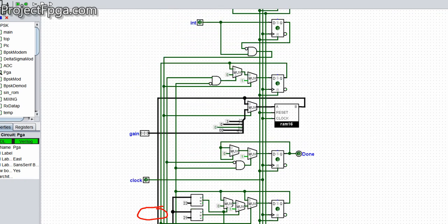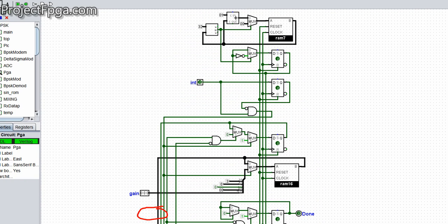The first part of this circuit is the clock frequency divider. Just like I told you, the frequency divider is a fundamental circuit you have to learn when you are dealing with Verilog. Because in practical sense, most of the time you might have multiple sub-circuits being operated at different frequencies.